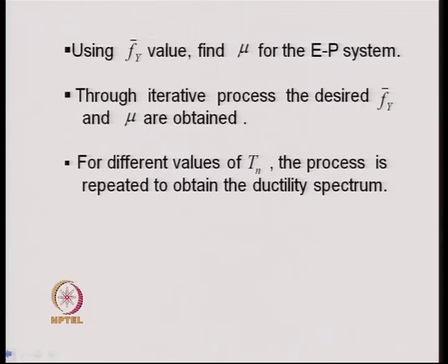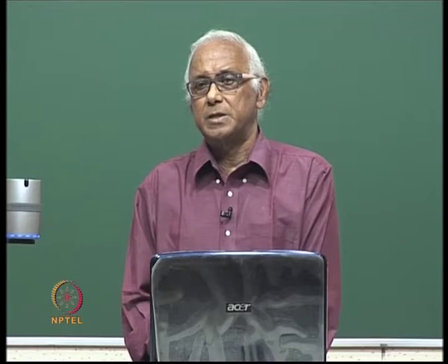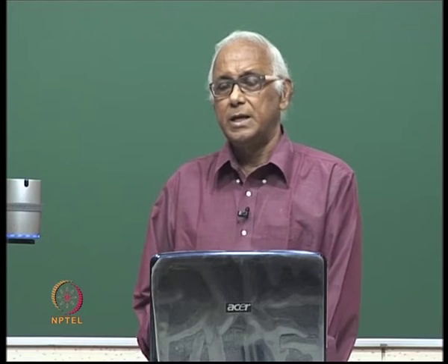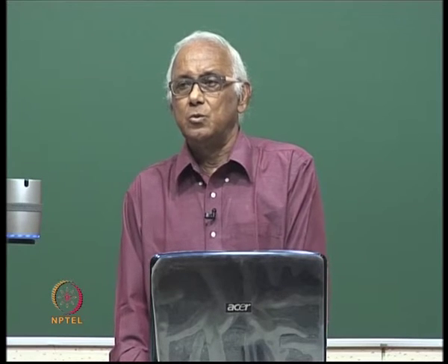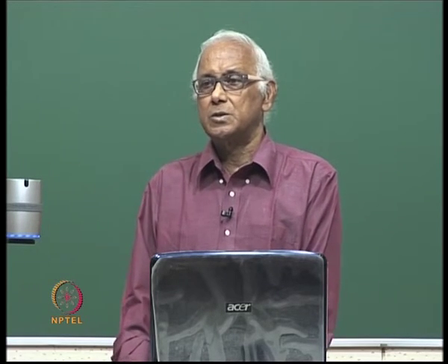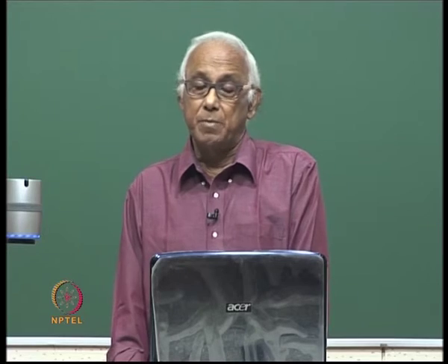So, once we know that, then it is possible for us to obtain the values of x y, a y, d y and v y. So, the inelastic acceleration, inelastic displacement, inelastic velocity can be obtained provided we know the value of yield displacement, and to know the value of yield displacement we must know the yield strength, and to know the yield strength we must know the value of f bar y.